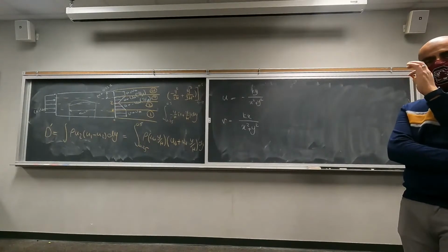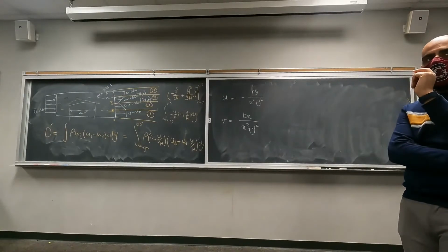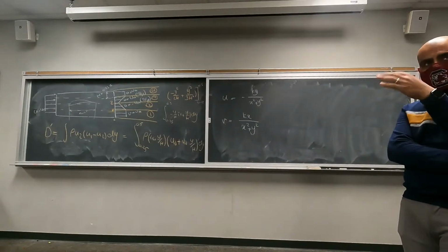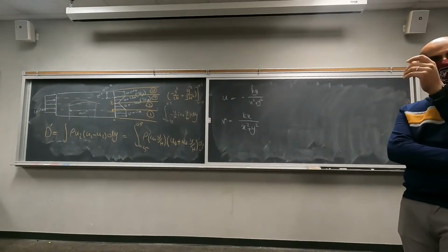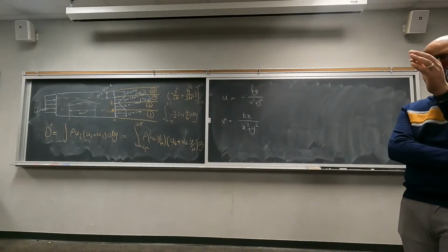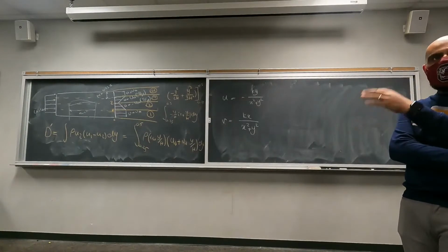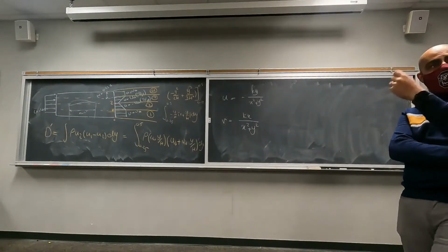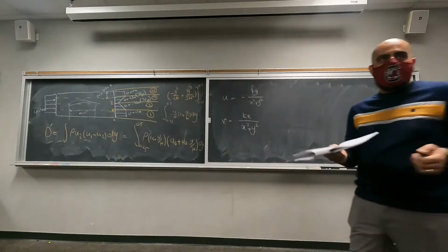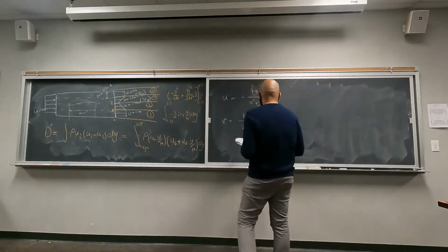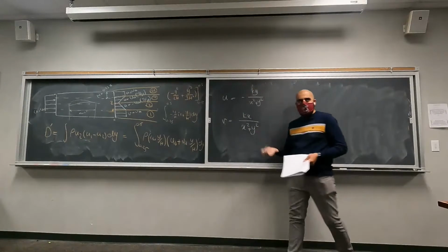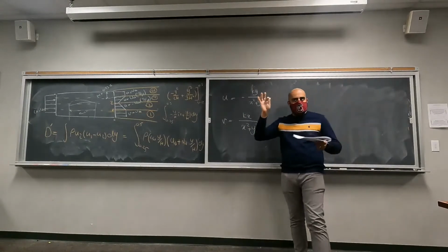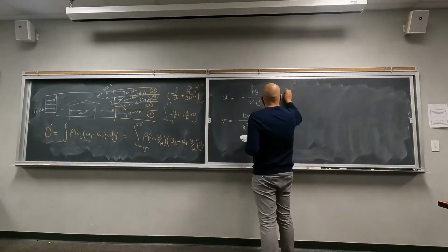Okay, so we are dealing with an incompressible equation. How can you simplify that? Exactly, and you can take all the rho out of the differential, take it to the other side. So essentially, you're going to have partial u partial x, plus partial v partial y, plus partial w partial z equals 0, or the divergence of velocity is 0, right? And we are dealing with a two-dimensional flow, so w, the third term, is 0 by itself.